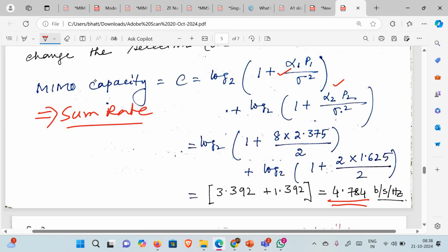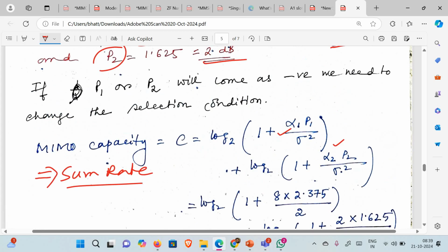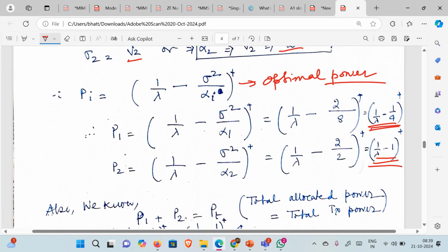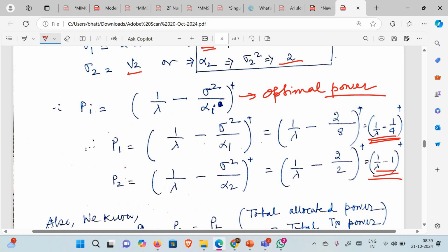So two things we have found out quite easily, in fact. If you are given this question, you might get a problem that has two parts. One part is to calculate the SVD separately, which we have opted out here. So you have to find a way of solving the SVD correctly, and after you have done the SVD, get the value of sigma 1 and sigma 2 or sigma 3, whatever it is, and calculate the channel gain. After you have done the channel gain, go back to the basic equation that we have for the optimal power, and find the value of 1 by delta, that is most important.